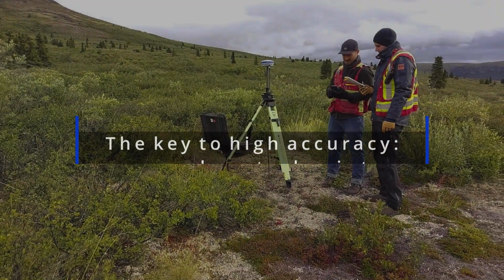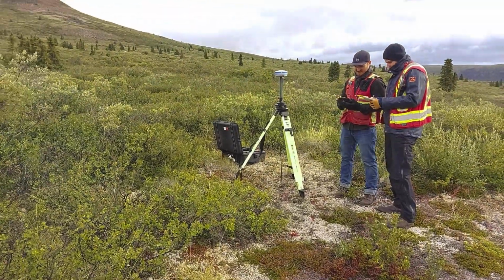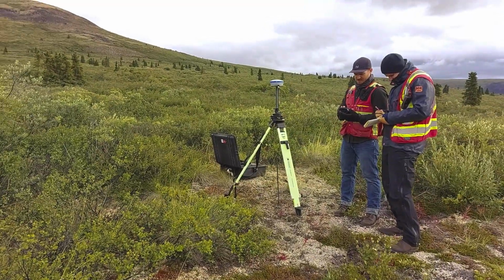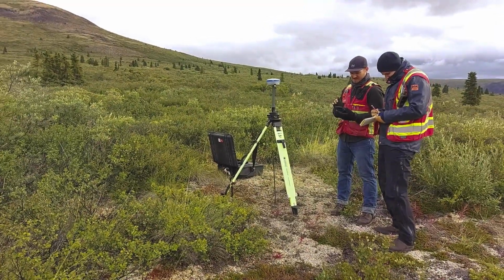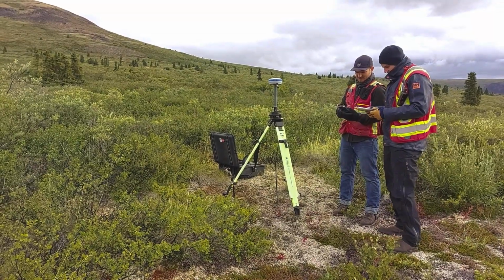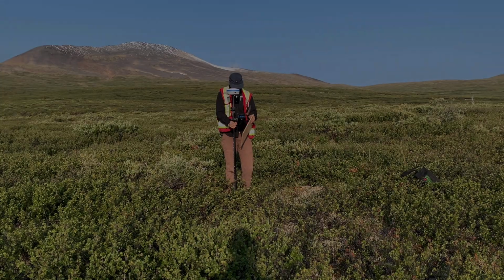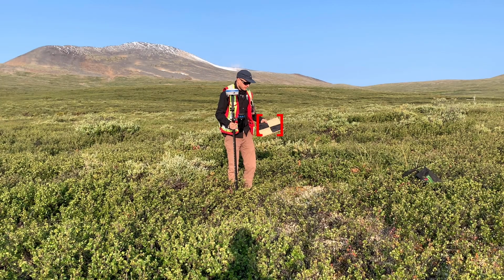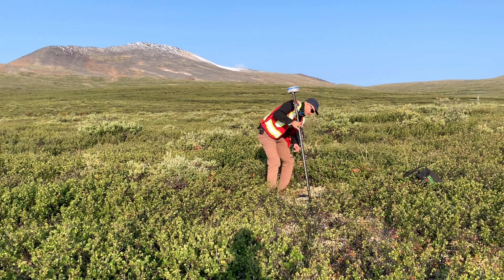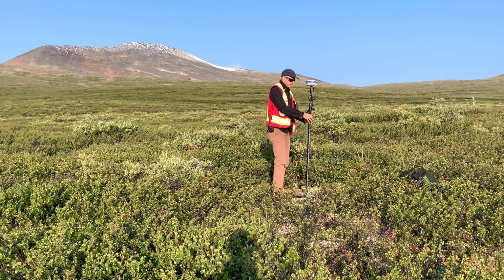Before we move on to potential applications of these technologies, it's important to point out that any remote sensing operation requires extensive ground truthing. Location, both vertical and horizontal, are ground truthed by placement of ground control points, as seen here. These are small targets visible by the sensors, which have been marked by a survey-grade Global Navigation Satellite System, or GNSS receiver.